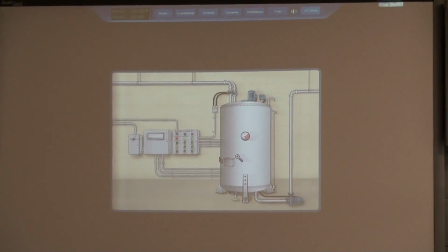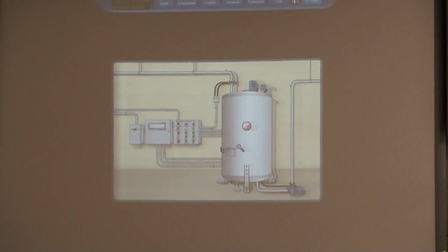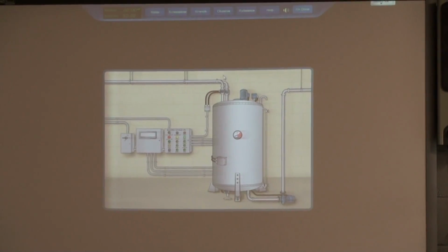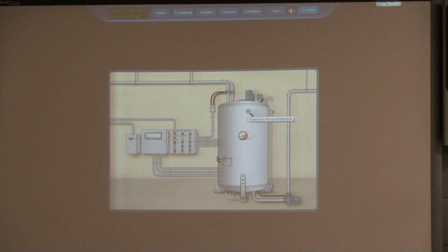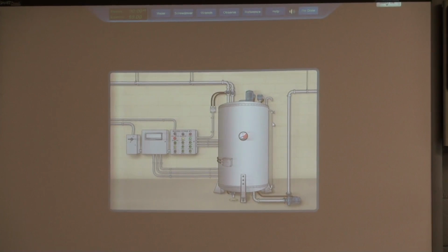But basically what happens when we press start is one pump, and we've got a pump up here and a pump up here, pumps in some amount of fluid, and the other one pumps in another amount of fluid. It's supposed to reach around 85%, usually on the sight glass that you see right here, somewhere around that area. Once it reaches that, it begins to mix the fluid after a time, and it mixes it for a certain length of time. It heats it. And the idea is to get to a set temperature, which can be seen on the indicator there. I'm going to zoom in on all these.